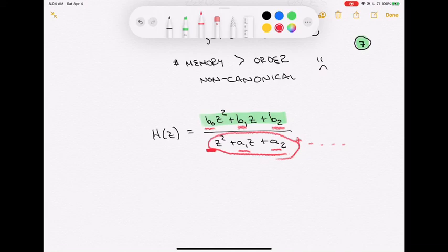So we've got direct form 1. Direct form 1 has zeros leading to poles. That's good. It is non-canonical, and that's not so good. So we would like to look at some different structures.